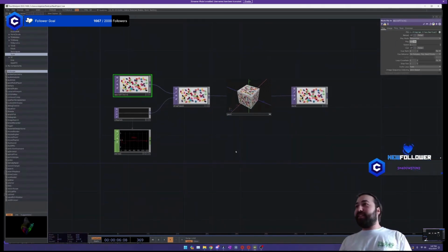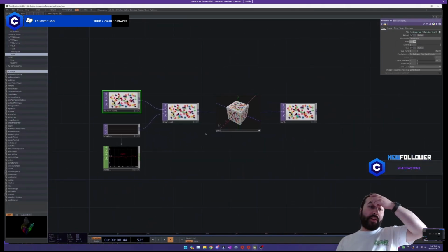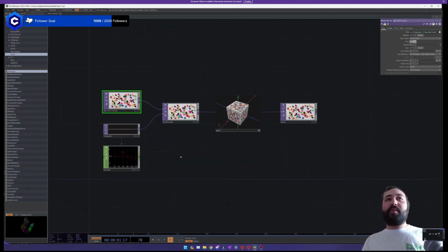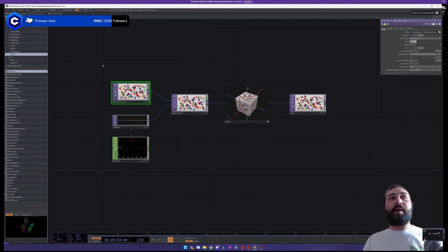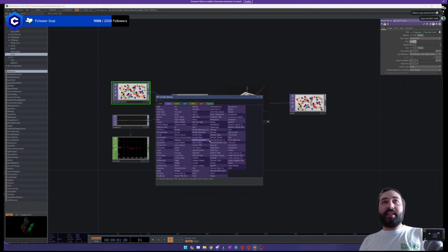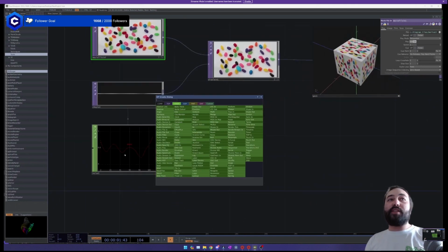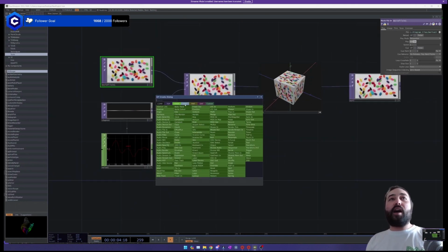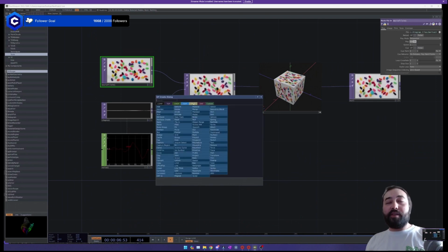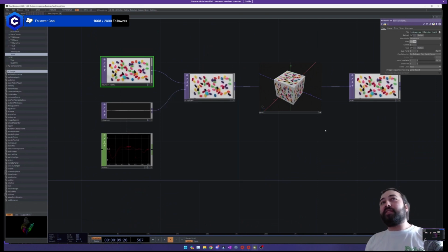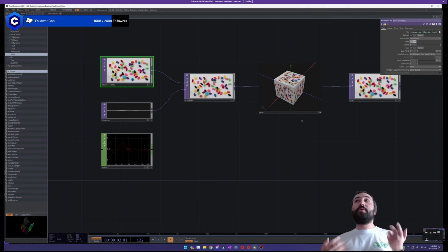So this is TouchDesigner. For those of you who have never interacted with it, it's a node-based program, not too dissimilar from Comfy, but it's built for real time. It's based on Houdini, if you've heard of that, and it basically lets you connect anything. There are many different types of nodes. The TOPs deal with pixels, so these all generate or manipulate pixels. The CHOPs generate channels, like this noise here, and values that change over time. SOPs are 3D meshes. DATs are basically like spreadsheets. With all these things combined, you can do literally anything.